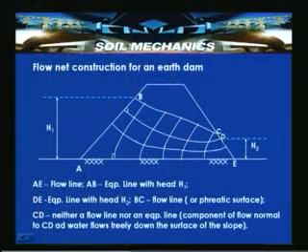So, here if you look into the small zone where the CD happens to be a point, it qualifies both as an equipotential line as well as a flow line, because there is a flow occurring perpendicular to that particular portion. If you look into the zone very close to CD, there is also a chance that the flow can take place downstream along the slope.